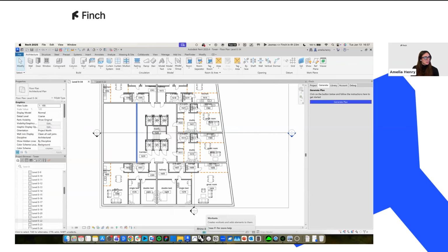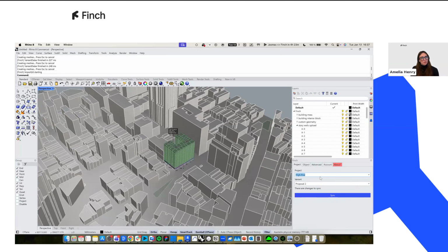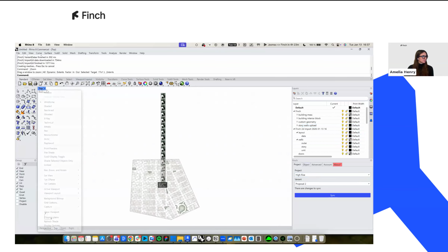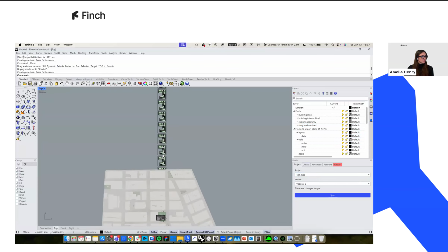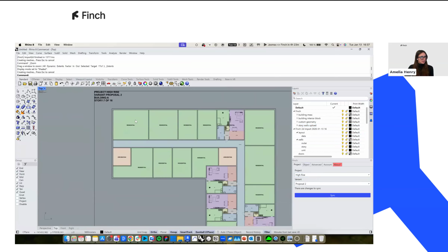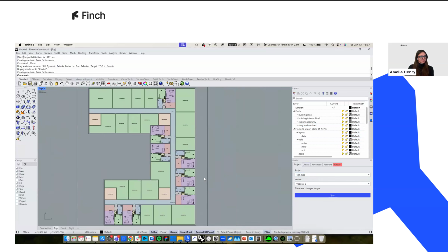All right, I'm thinking last thing I'll show is actually bringing out into Rhino as well. If we just go ahead and want to bring in a 2D model of our CAD drawings here, let me just import that. We're going to receive some geometry right here into Rhino. All right, there we have it. So let me look at my top view, see what we have. Zoom in there. And so here we can see that project that I was working on brought down into Rhino. We see that we get a different floor plate, and we're bringing in both surfaces, curves, blocks. So you have a lot of geometry to work with here as well.